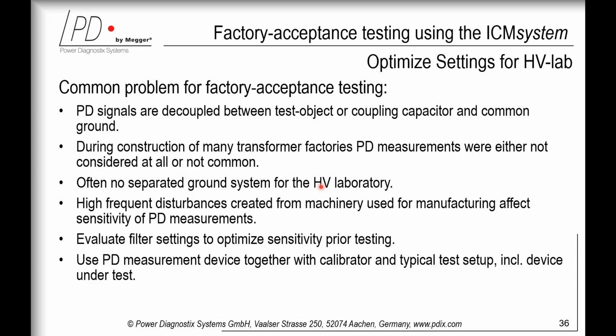The second point worthy to mention here is the fact that the shape and height of disturbances received may vary over the day, again depending on whether someone is welding, or if a cherry picker is charging, or a crane is moving, or similar. If the engineers doing these measurements are not aware of the context, it may become hard to understand what's happening and why. This often leads to the conclusion that this PD thing is somewhat unpredictable, but usually it's not, it's just physics.